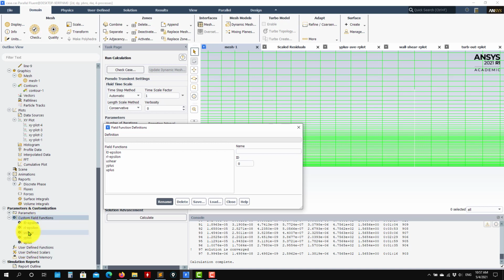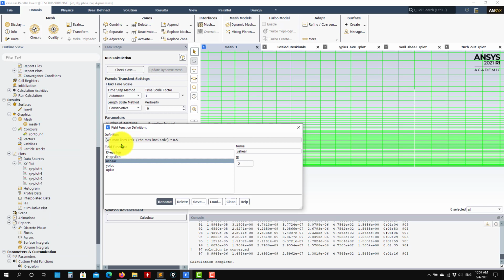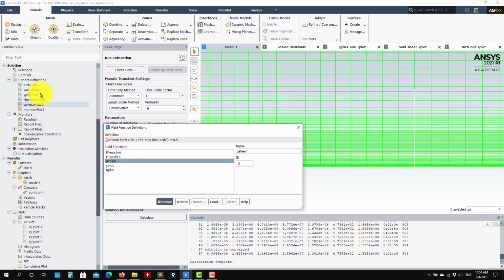So see that we have shear velocity. You have it here. This is how I compute it. I created a sample, and here I'm accessing this line. In this line, I'm sampling the velocity and the shear stress. So the shear stress at this point divided by rho at this point. In this case rho is constant, so you don't need to do it, but I just did it to make it general. Then a square root of that.